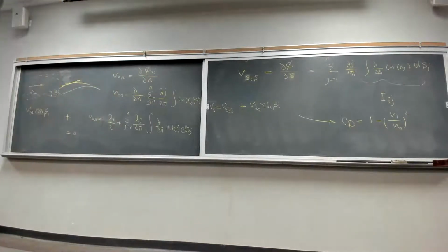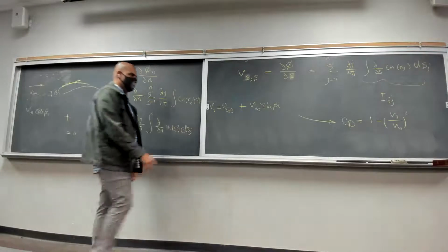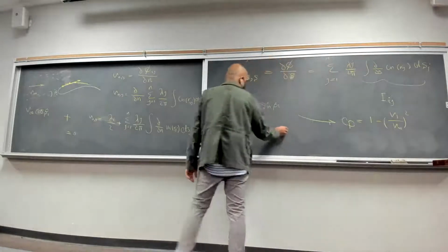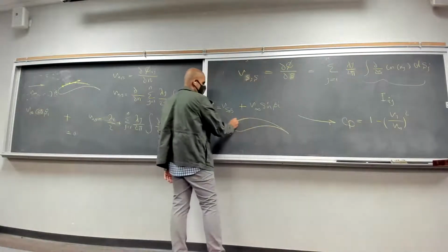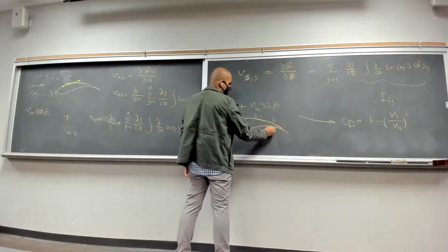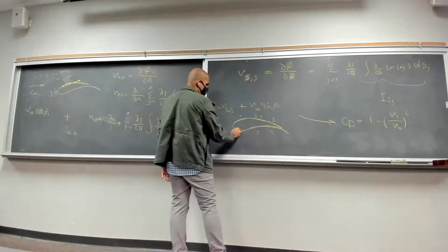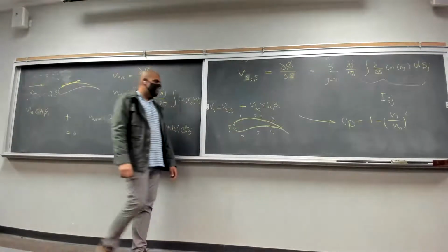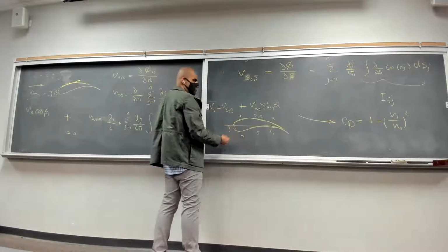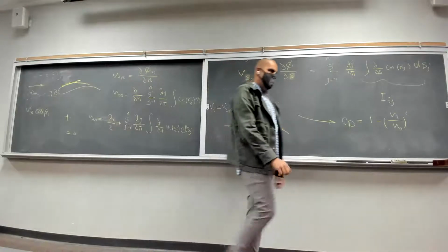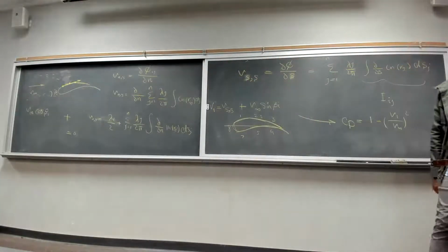No, there's no other summation. Your goal here is to find the CP, right? When you have the CP, let's say you have the value of CP here. Here you have the CP1. CP2 is 2.5. CP3 is 3. CP4 is 4. CP5 is 5. CP7 is 7. And CP8 is 8. When you have the distribution, you can use the equations we already have. Integral of CP lower, CP upper, dx to find the lift and drag coefficient.